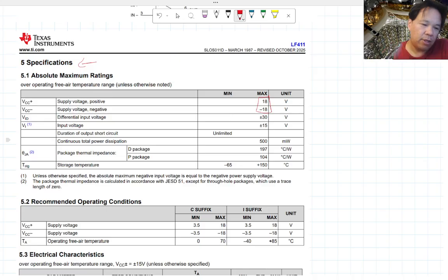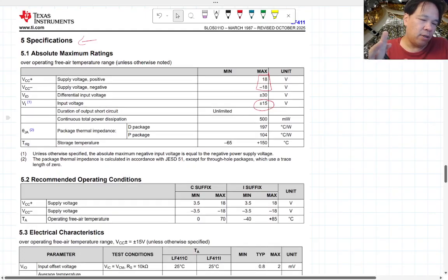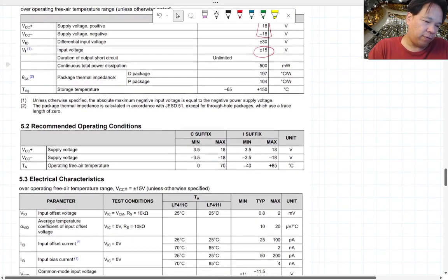voltage you can actually put at the voltage supply, so this is VCC and VEE, is 18 volts. If you put technically 18.1 volts on it, maybe, right? Even at 18 volts, if there's a little fluctuation in your DC power supply, you're going to start breaking the circuit inside. So don't put anything above 18 volts. In the lab, we're just going to run it at 15. And you want the input voltage to be less than 15 also, because you may have cases where the gain is less than 1, but your input still has to be less than 15 volts.